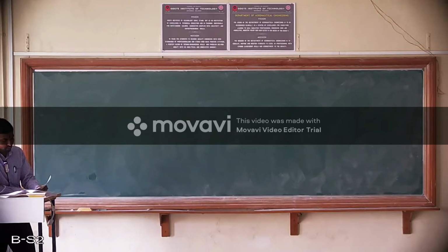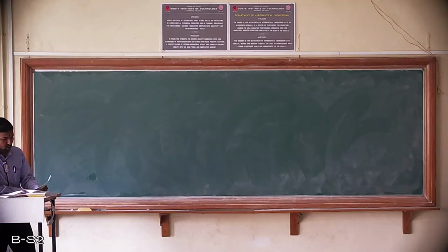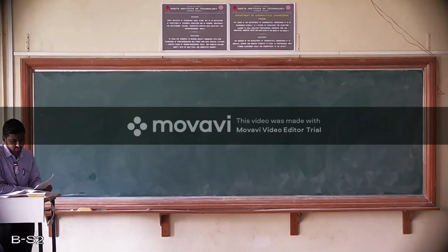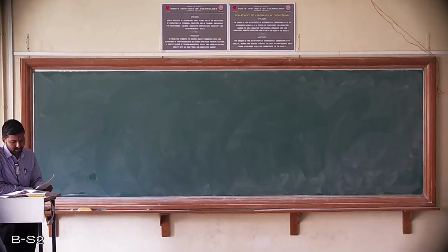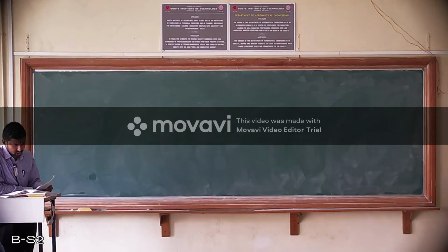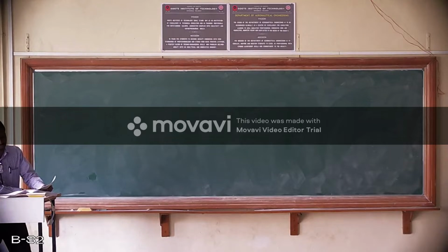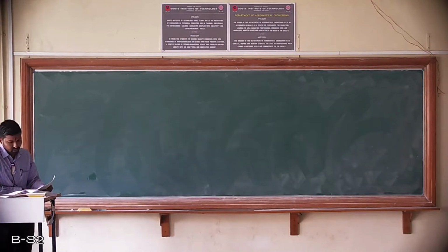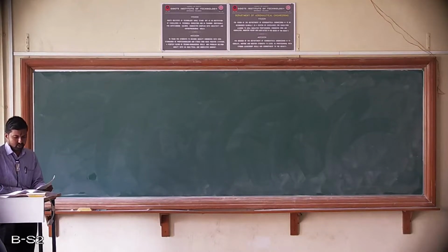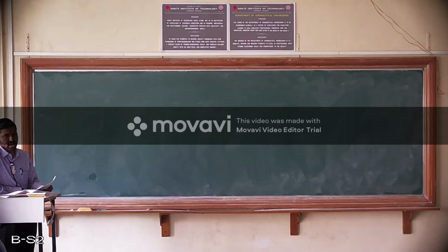Each arm of a Porter governor is 250 mm long. The upper and lower arms are pivoted at lengths of 40 mm and 50 mm respectively from the axis of rotation. So this is a very, very important statement. It means the upper arm is pivoted at a distance of 40 mm from the axis, whereas the lower arm is pivoted at a distance of 50 mm from the axis of rotation. So both the upper arm as well as the lower arm are not at all attached to the axis of the spindle. Very, very important.